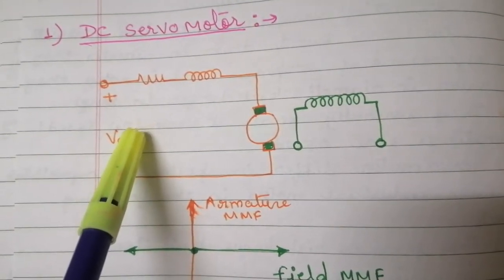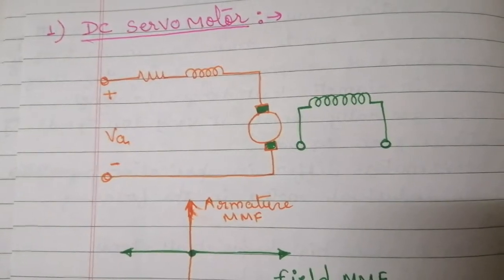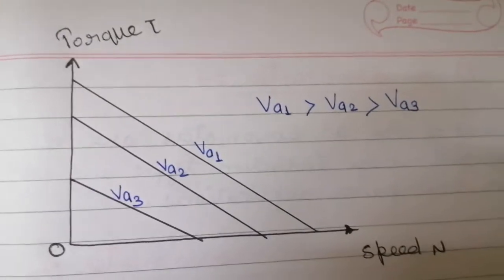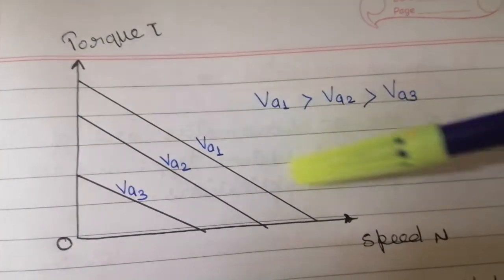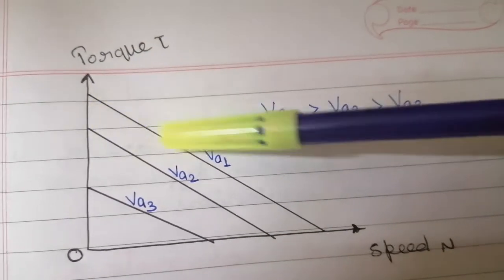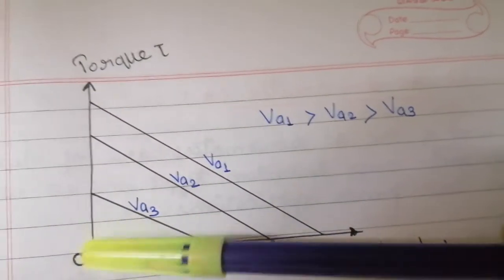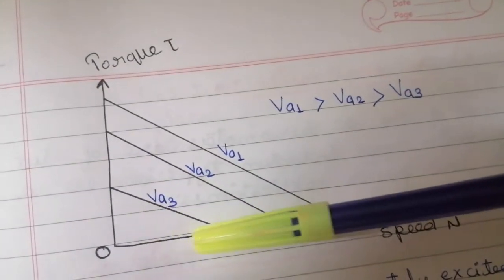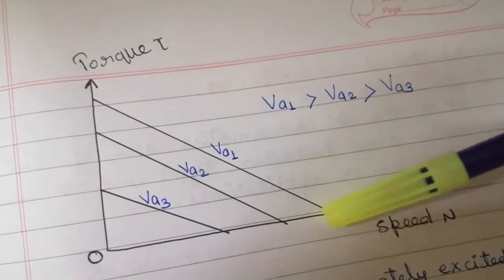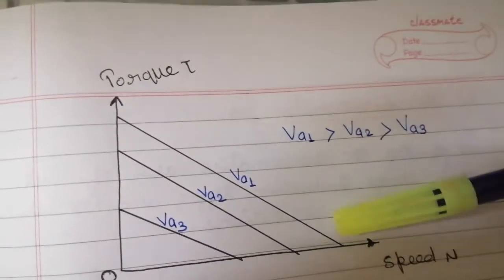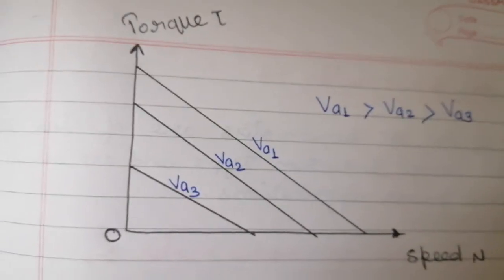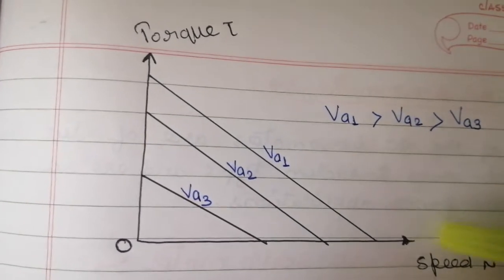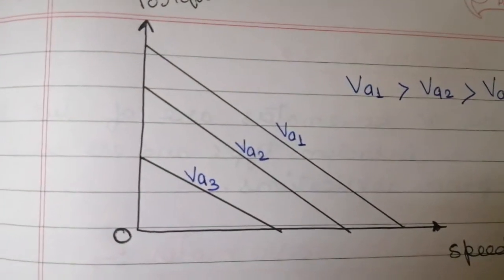Look at the torque speed characteristic of the motor. See, this is the torque speed characteristic, where the characteristic is more linear and has a large negative slope, meaning at zero speed torque is very high, and as the speed increases torque decreases very steeply. And this large negative slope provides viscous damping for the servo drive system.